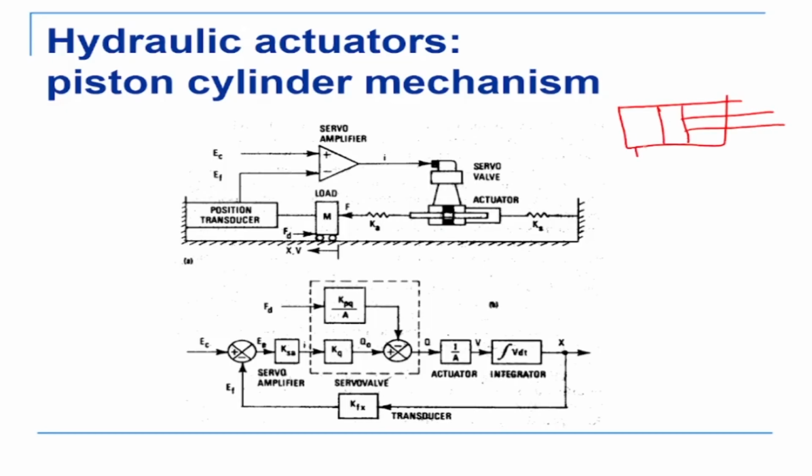Okay, so there's an input here and an output here. So in here, out here. Okay, so if you charge the cylinder, what will happen? The piston will move this side, and this will come out. Now if you charge this side, then what will happen? The piston will move this side. So by giving pressurized air or pressurized liquid, you can make it move in any direction.